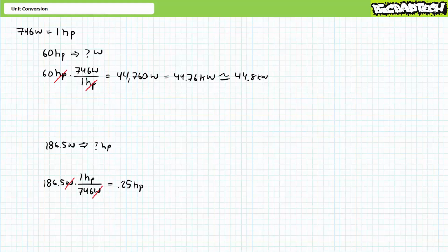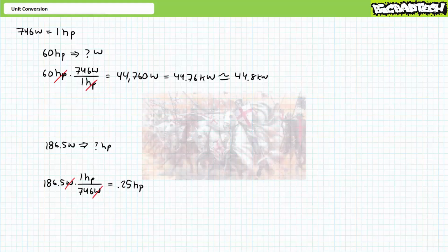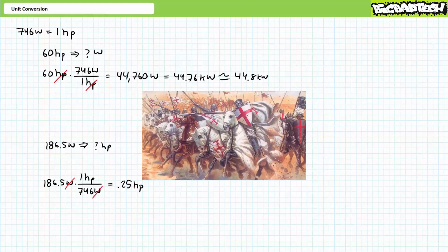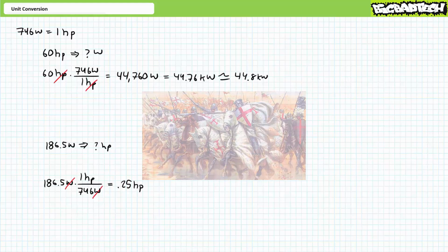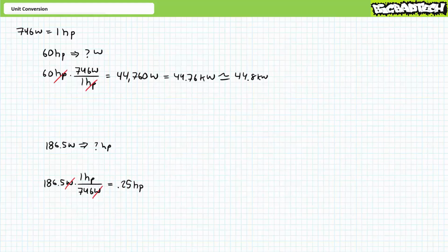Also, the unit of horsepower is a great indication of safety. Think about it. Can a horse kill you? You're damn right a horse can kill you. A horse could smash you to a bloody pulp. Be extremely careful when you're working on actuators greater than 1 horsepower or 746 watts. Returning to our example, could a quarter of a horse kill you? Like, could a kick from one leg of a 4-legged horse kill you? Yes, it could, depending on where you get hit. Be careful when you're working with quarter horsepower motors. In fact, be careful of any device capable of exerting power in any portion of your anatomy you wish to keep in working order. Moving on.